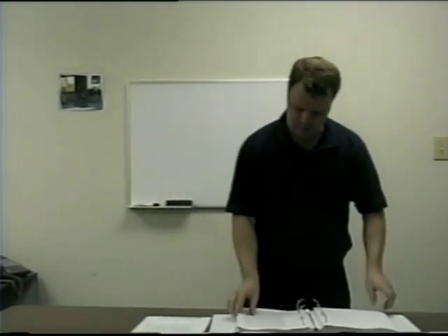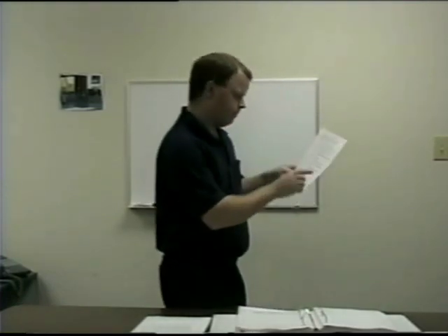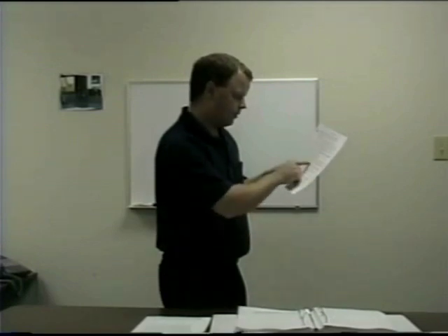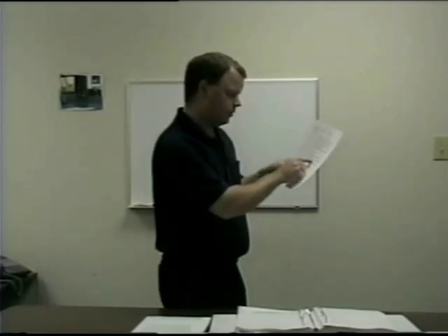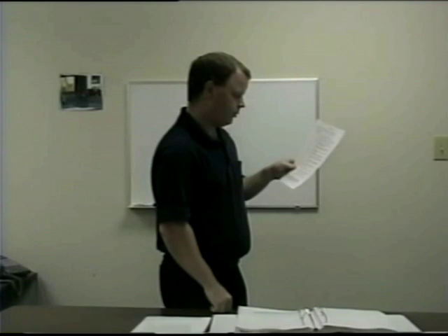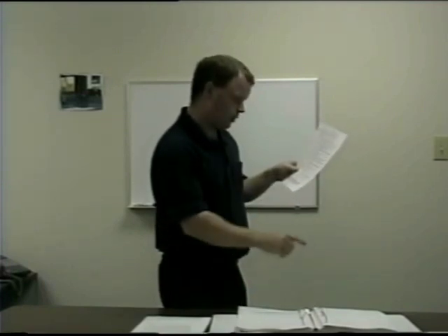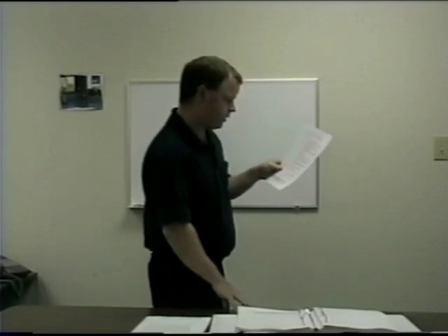Let's look at some more examples. Metal windows. Verify windows are sealed as required for metal-to-metal surfaces and other surfaces. Observe that solid grouting, caulking, and backup are provided if required.